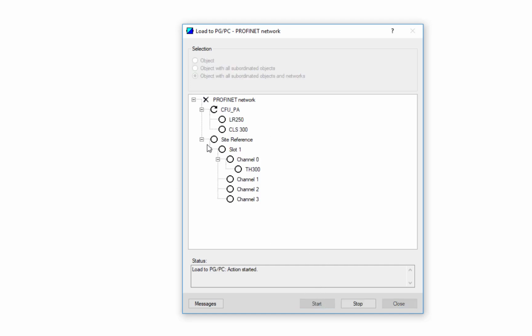When I start my communication, I can see that it's communicating with the instruments and uploading them. Here you'll see this is a Profibus PA radar, a 26 gigahertz radar. If you've ever used PDM on a Profibus DP to PA coupler, with one device it's okay.